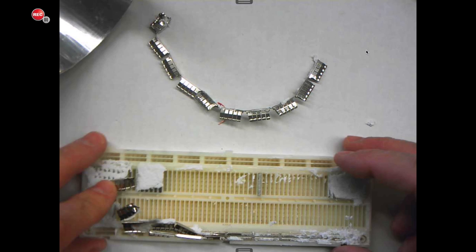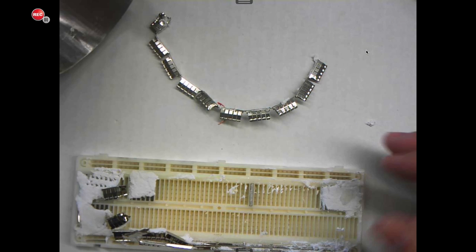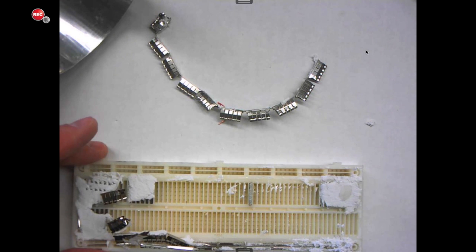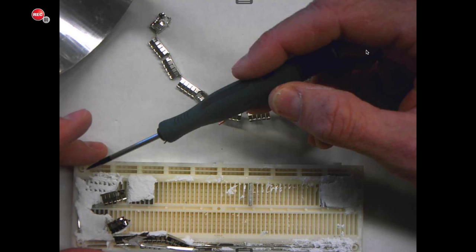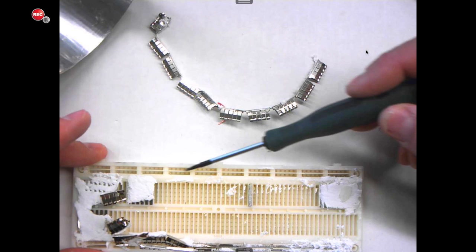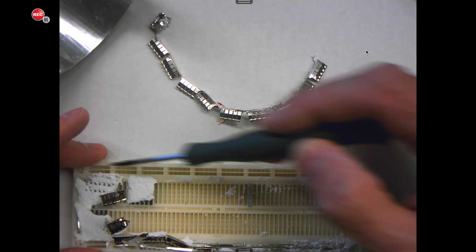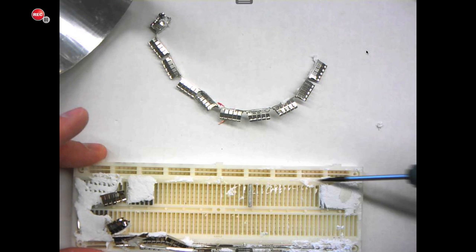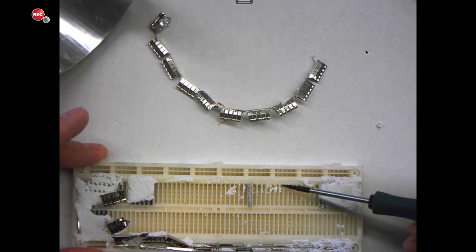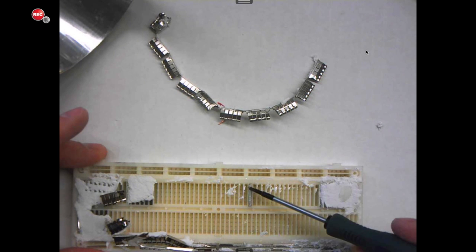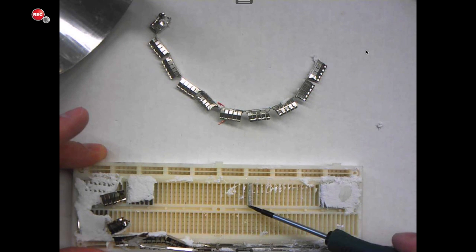Now if I lay it flat again, you can see now quite clearly you have these sections at the top, which are the rails that are connected horizontally. And again, this rail is not connected to this one. They're separate. Then there's this divider here. And then you've got these little conductor sections here, which have 5 holes and columns, we'll call them.